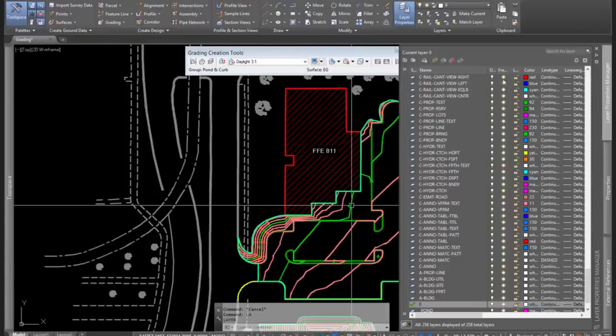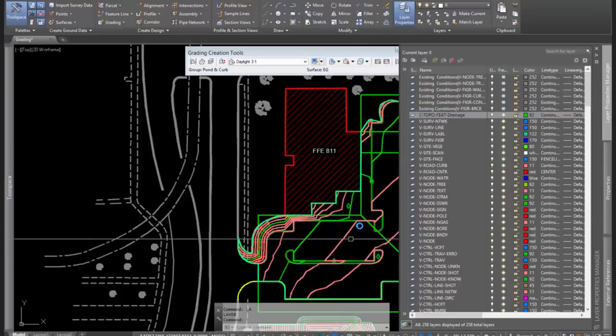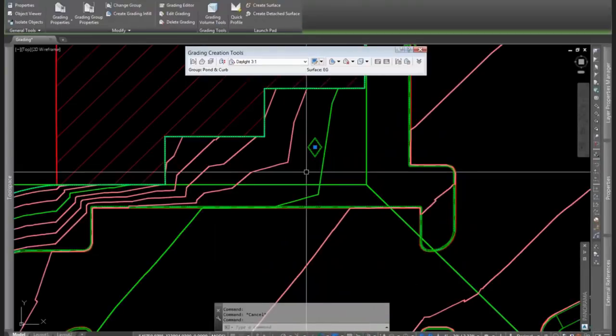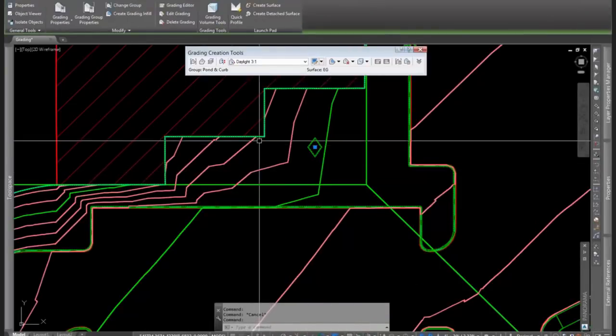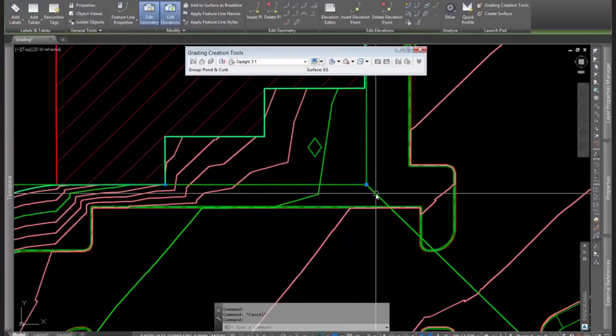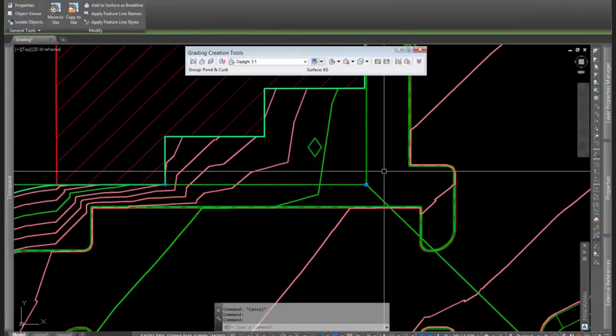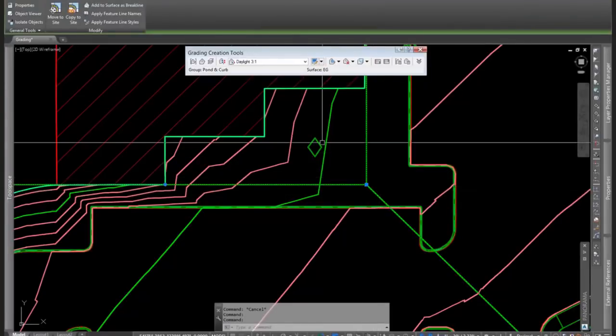So let me open up, let me turn on those drainage feature lines. I was able to put this infill right in here, and this fills this whole area in between the building and the back of curb. If these drainage feature lines right here, these ones I have selected, if those are in the same site, they're going to interact with all of this. They're not going to allow that infill.